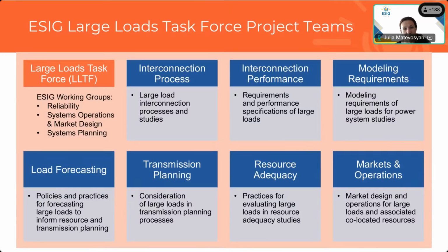One is focusing on interconnection process and studies. One is focusing on interconnection performance, what requirements are needed to ensure reliable operation of large loads and reduce any unwanted impacts on the grid. Modeling requirements, which is primarily focusing on how large loads should be modeled for stability assessment. Large load forecasting, which is forecasting looking longer term, so it's not the operational forecasting that we're covering here. Transmission planning, how to consider large loads as we are planning transmission, and resource adequacy, how large loads should be included in resource adequacy assessments.